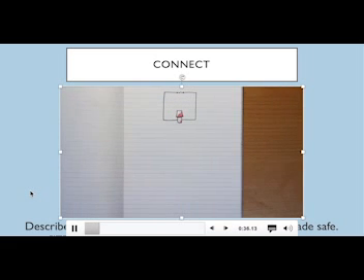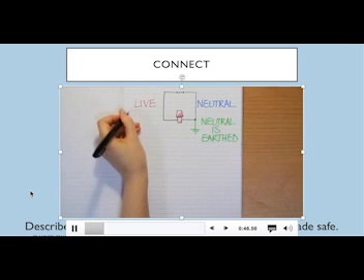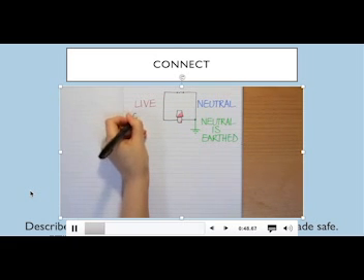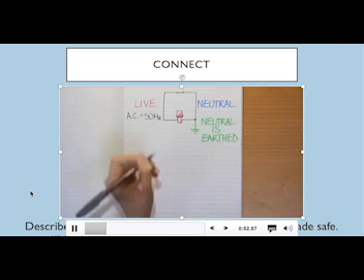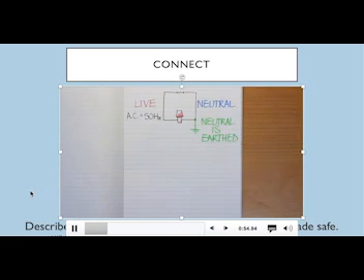Instead, one wire is said to be neutral and is literally connected to the earth at your local substation, so it's relatively safe. The other is called the live line, and its potential, or voltage, becomes positive and negative relative to the neutral line 50 times a second. This is why we talk about mains supplies delivering alternating current at a frequency of 50 Hz.